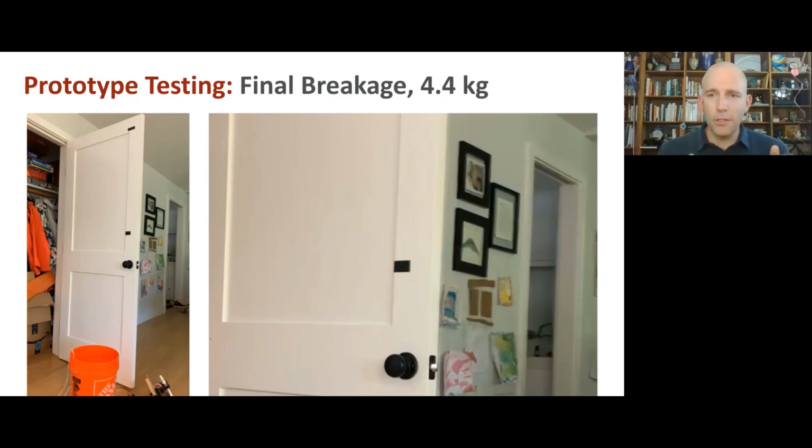And another little tweak that I would have made is to give the payload rope a little bit more trail. So as that offset, the vertical offset of the wheels got smaller, I want to attach the payload rope below the lower wheel so that it would have this restoring moment as the heading changed, and maybe a separate adjustment for that rope attachment point. So that was my design.